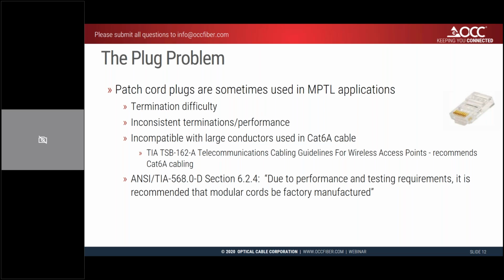One of the biggies though is that these plugs are typically incompatible with larger conductors and larger cable diameters of, say, Cat 6A cables, which is typically recommended to be installed. It's hard to find a patch cord plug that will actually accept these things and do it correctly.